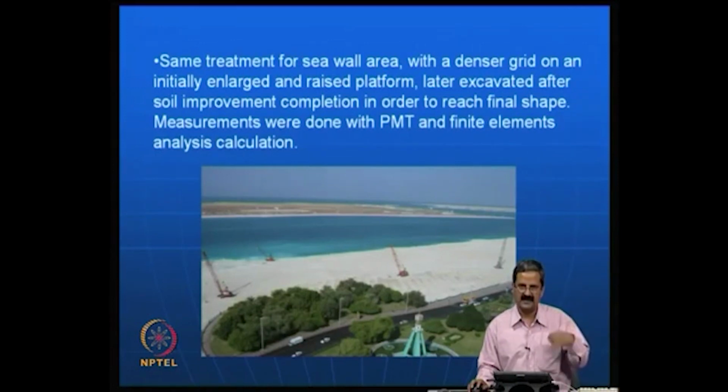If the stresses are going to reach a very soft area, then the problem is that it could lead to a lot of settlement, and one should optimize so that those settlements do not occur. These are some of the issues that one needs to understand to see that dynamic compaction is done in a proper way. There have been many case studies even in India, particularly in many coastal areas, where dynamic compaction was done, and in fly ash ponds it was done.